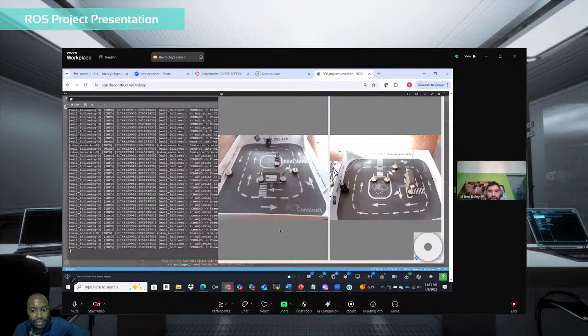And here, if you can notice the dead zone thing I was talking about. Right now it's within the dead zone and it's basically doing small deviations towards the right wall as it's going. I see, so it's within the dead zone and it just continues going, within the threshold, until it's facing the right wall. Let's see how it does with the obstacle right there. Okay, perfect. It goes through, it's within the dead zone range right now.